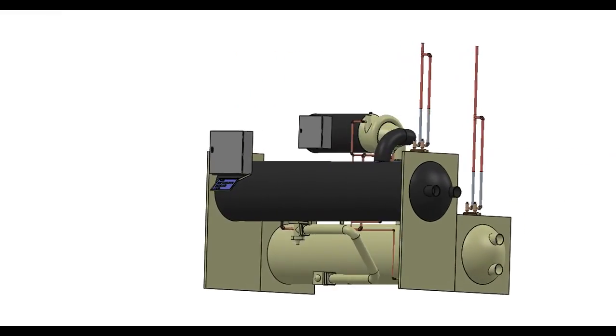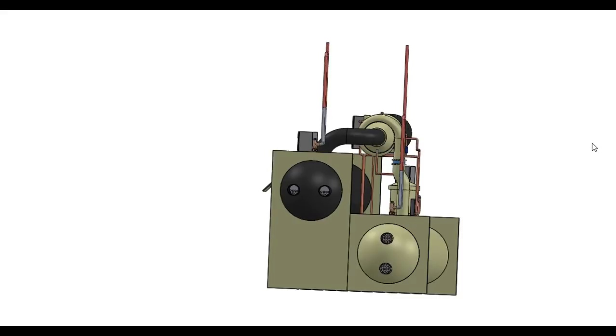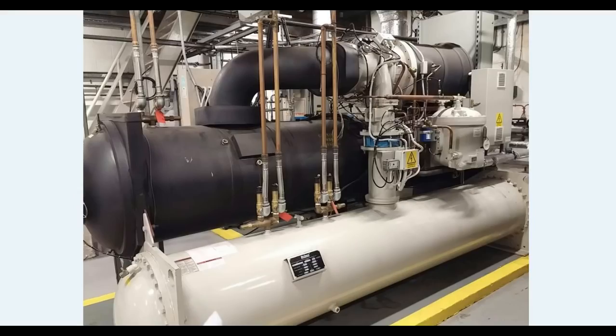So you should have written down the 4 main components and the 3 main circuits within every chiller. So I'd like you to now test yourselves. If we bring up this photo here of a real life chiller, the McQuay chiller, just apply your knowledge here. So take a few moments. Can you tell me what this cylinder here is? Remember, it's got a tube, it's being fed refrigerant off of the compressor, and it's coming down and entering the condenser.